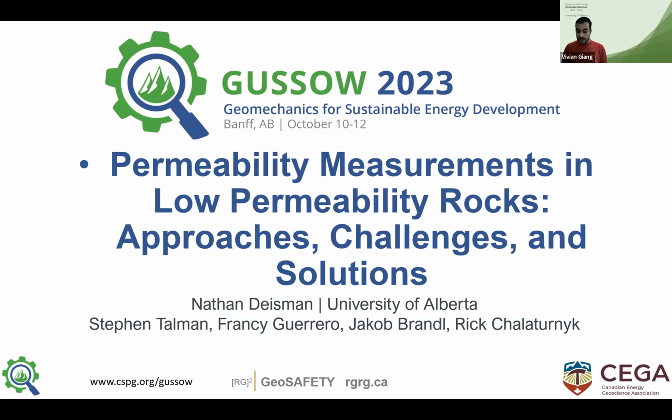We will discuss crucial aspects of the testing configuration and specimen loading, including sample preparation, specimen drying, resaturation, the impacts of test conditions on sensors, and their implications on the measurements and permeability solutions.